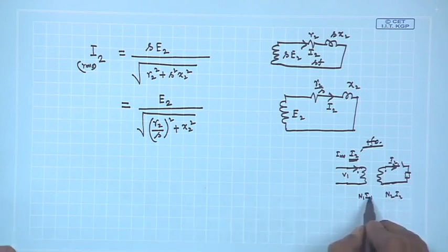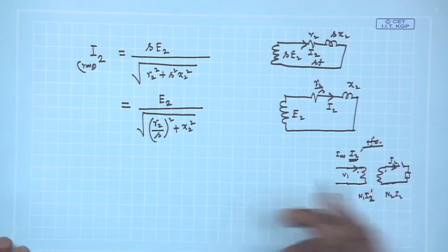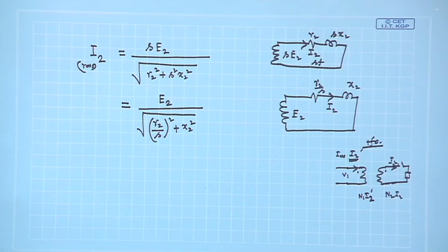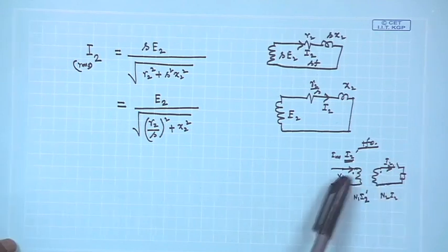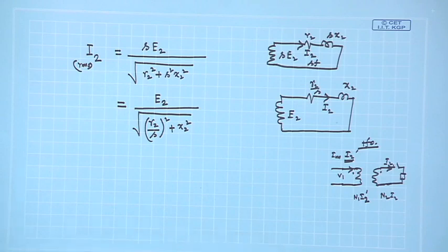N2 I2 is equal to N1 I2 dash, extra current it will draw apart from this Im, such that N1 I2 dash is equal to N2 I2. Look at the dot convention, their MMFs will always cancel out. Therefore, flux in the core will remain only due to N1 into Im, the magnetizing current.